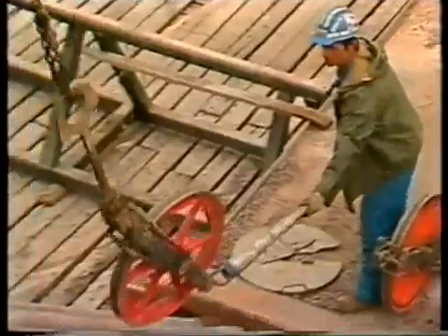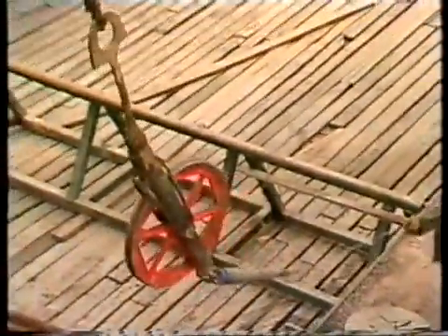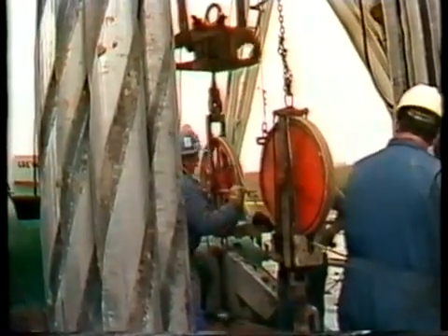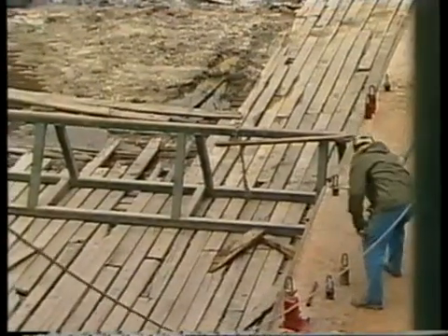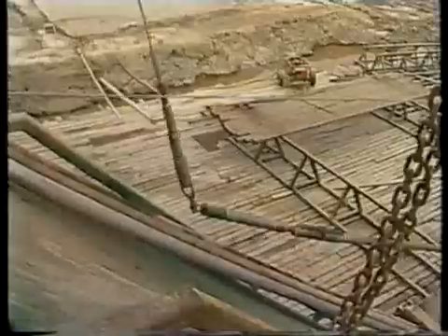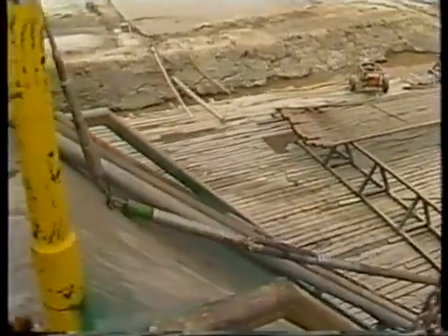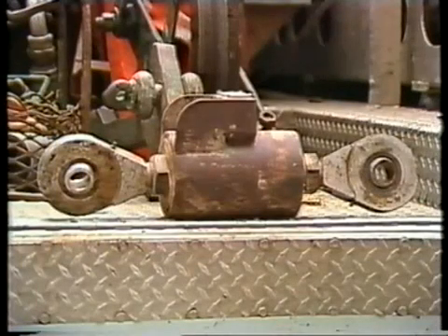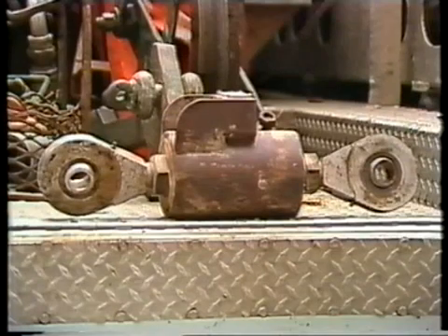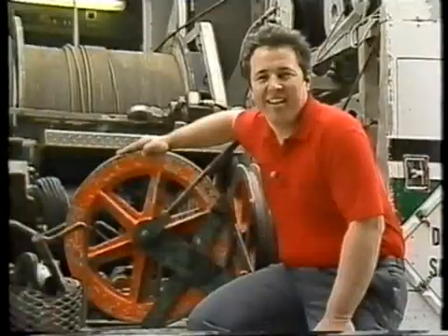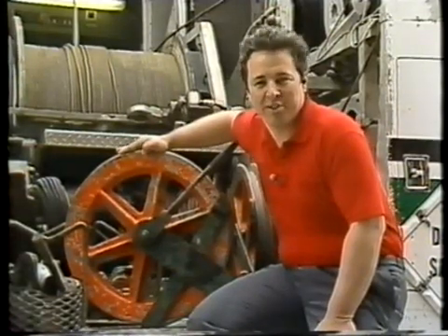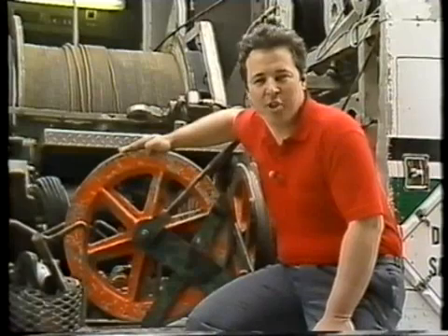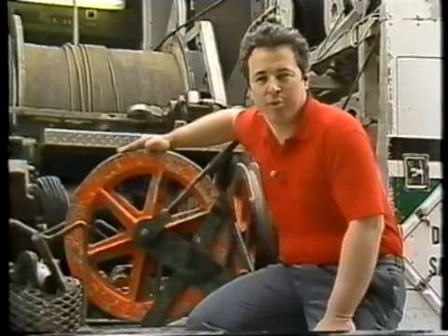This procedure includes hanging the sheave wheels, threading the cable through under the bottom wheel and over the top wheel, then attaching the cable head to the uppermost tool and raising the tool string. A cable tension gauge is always used and may be attached to either the upper or lower sheave wheel. It is important to remember that these sheave wheels will be points of maximum stress during the logging run. Care should always be taken to see that they are well secured.